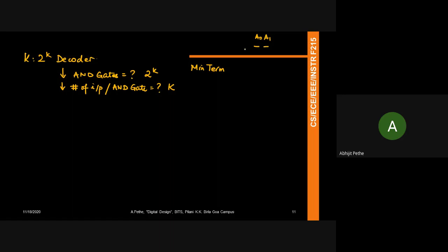Next, you can think of them in addition: you'll have K inverters also associated with it, if you don't have the complement inputs available. So in addition to K inputs to power K AND gates, you'll also need K inverters to design this decoder, right? So again, what you begin to see is as you start making the memory larger, right?